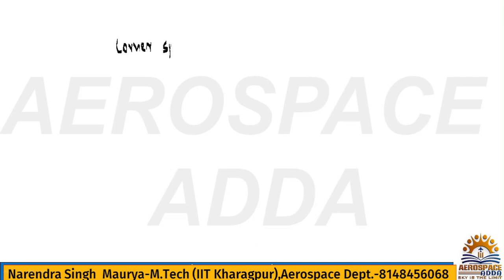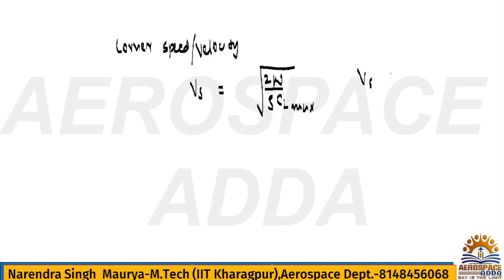I just want to explain this. Corner speed or velocity is called Vs, and sometimes it is also the stall speed. So it is the square root of 2W by rho S CL max, because it's a stall speed. So obviously Vs is inversely proportional to the root of CL max.